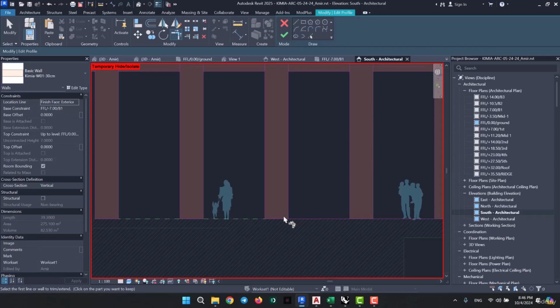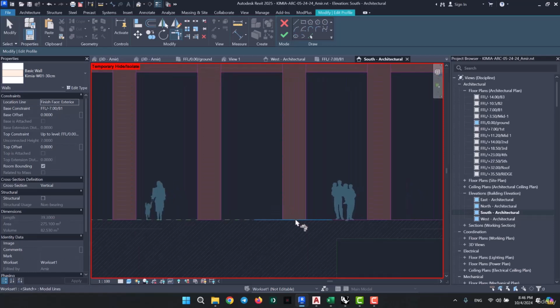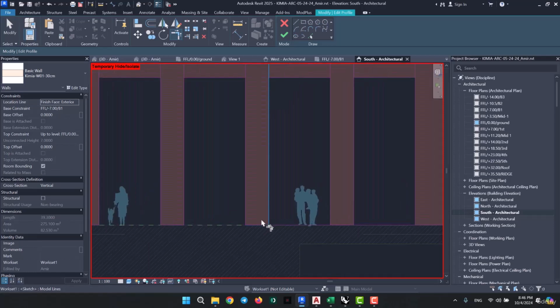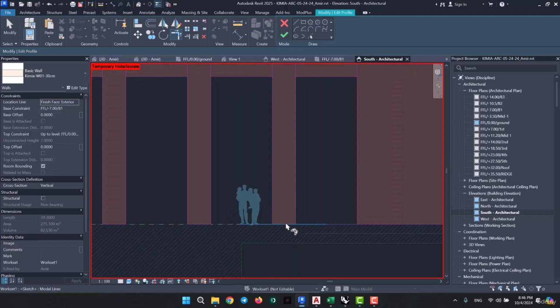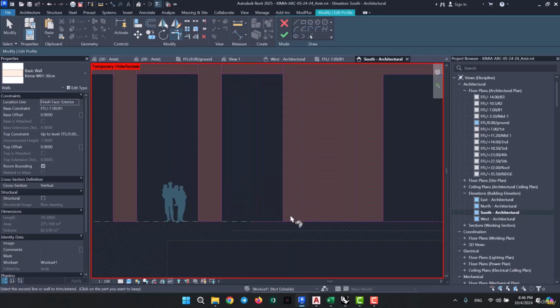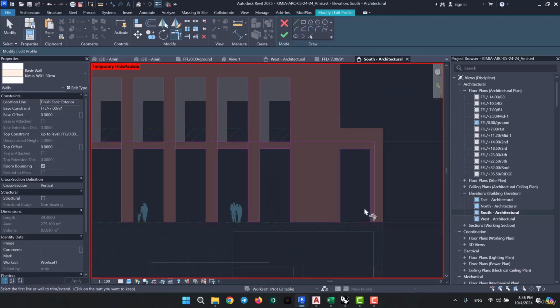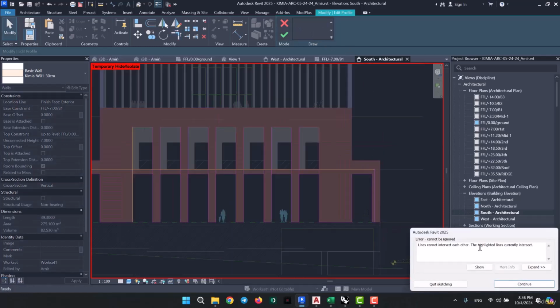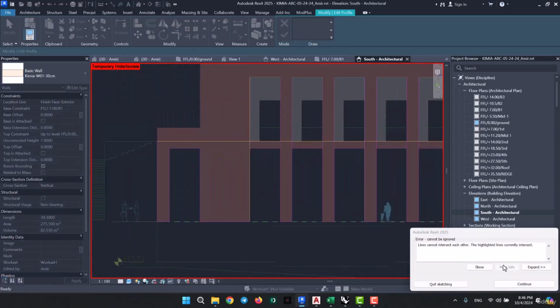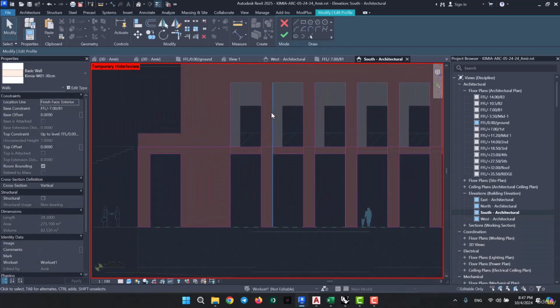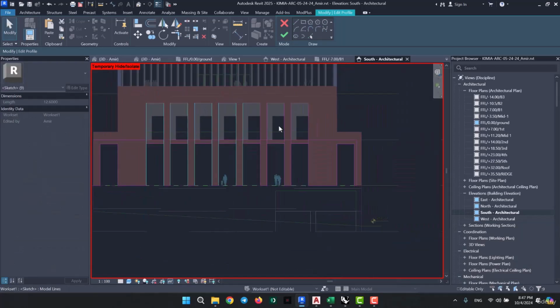What I'm doing right now is trimming some lines so I would have a clean drawing. Now I'm going to trim these two together, then this one with this one, and done. Click Finish. And now let's go back here. Looks like we've got some lines around here, which we might have to extend all the way down.